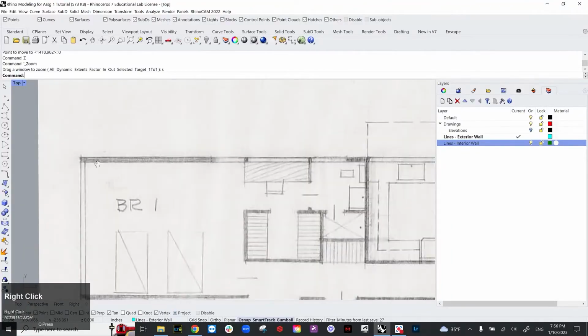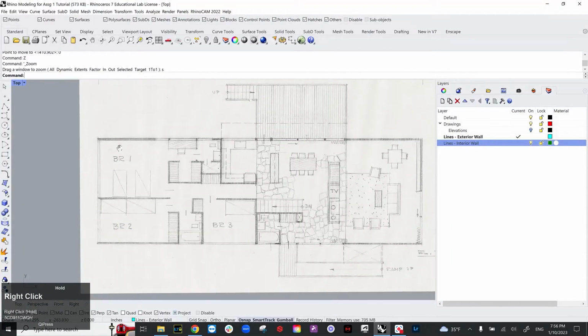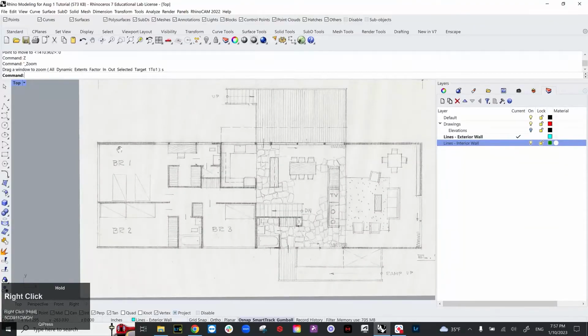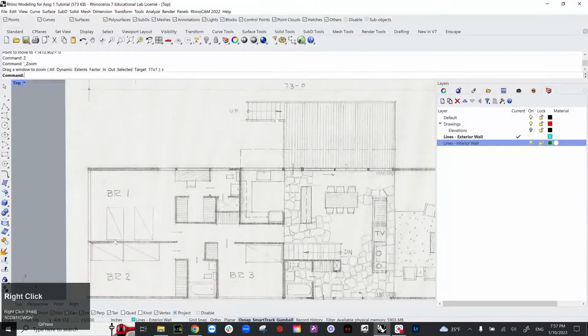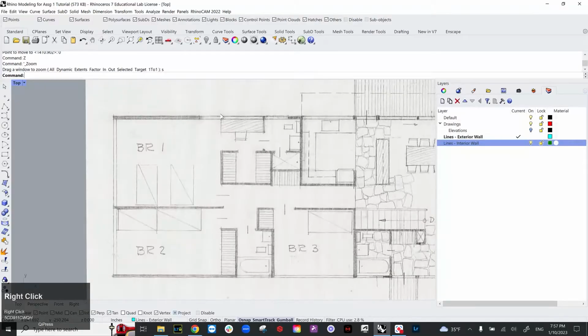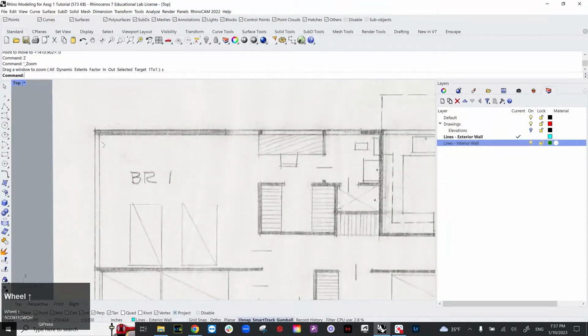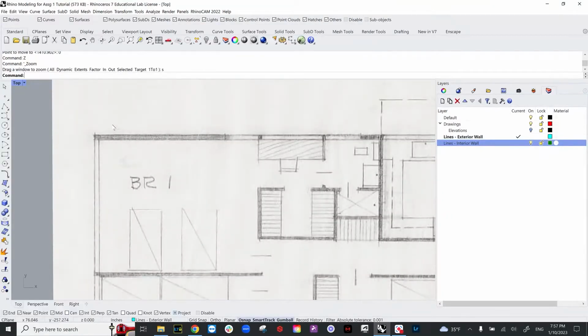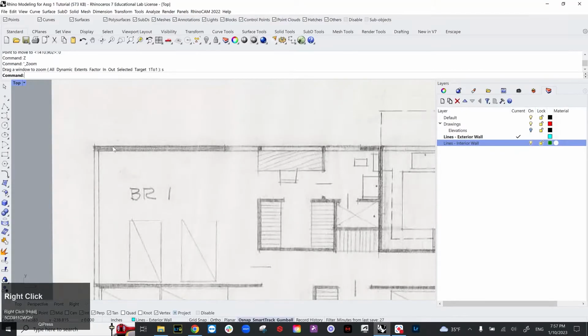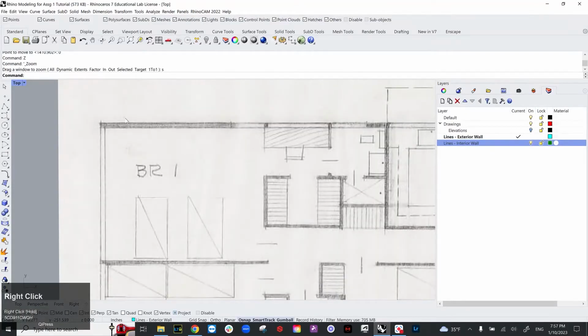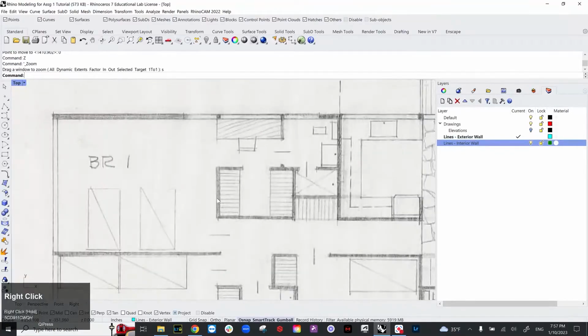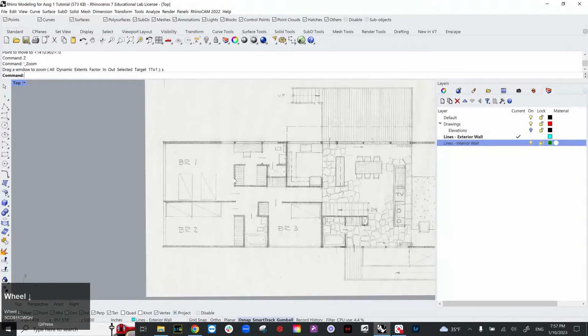So in general conventions at the schematic design phase, which is like the beginning of the design phase in architectural and design context, what we usually do is assume the thickness of the exterior wall to be 12 inches over here. So we will assume this 12 inches and then interior walls to be 6 inches.